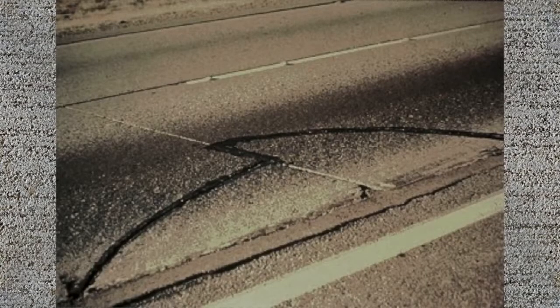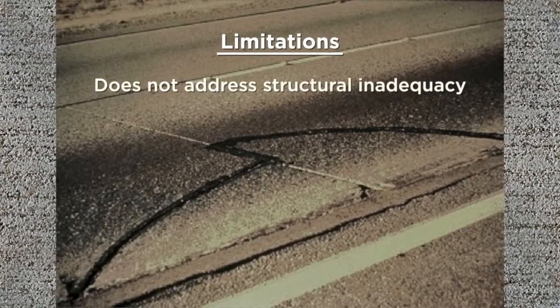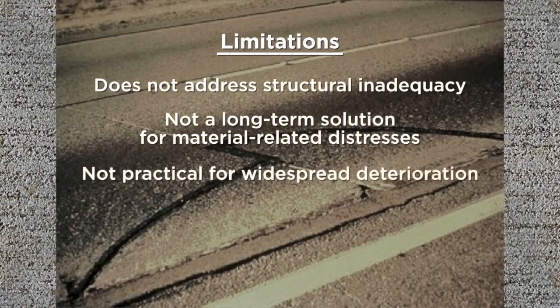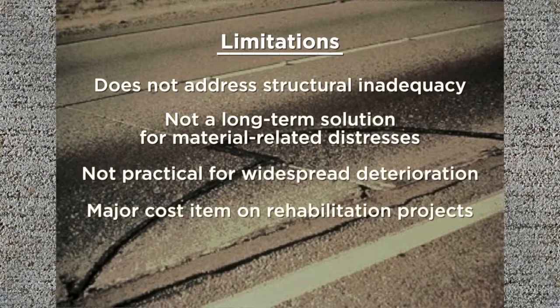However, concrete pavement patching does have some limitations. It does not address structural inadequacy. It's not a long-term solution for material-related distresses. It's not practical for widespread deterioration, and it's a major cost item on rehabilitation projects.